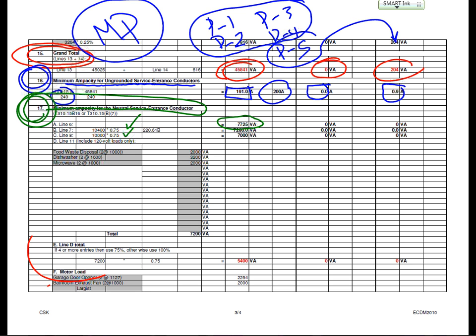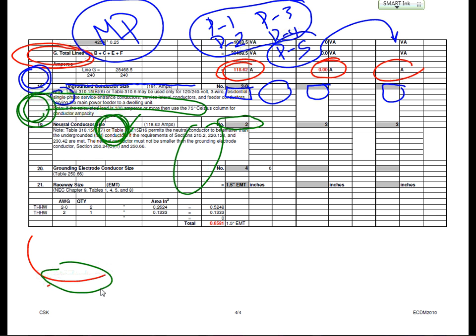So here are all the ranges and the dryers that need special treatment because they need a neutral, even though they're 240/120. So the code says cut them by 75%. And then we do all the calculation here, guys, the same calculation for the neutral. Can you guys see right at the bottom here? We have the motor load only, but look which motors we accounted for: only the motors that are running at 120. Anything that's running at 240, when it comes to the neutral, is a big fat 0. So we did the same calculation based on the neutral. That's what you did, guys.